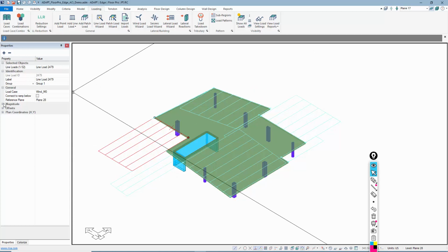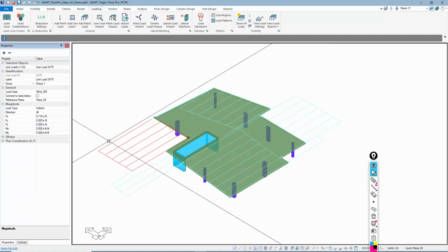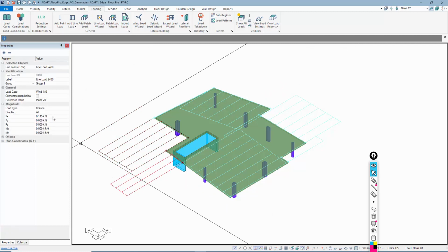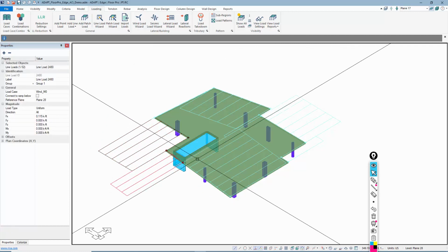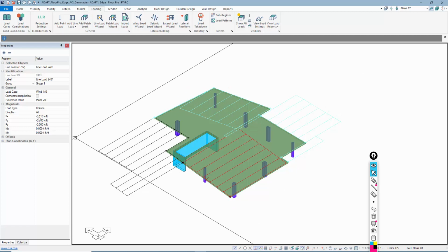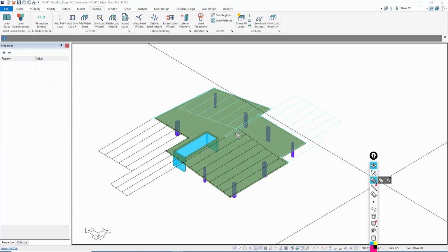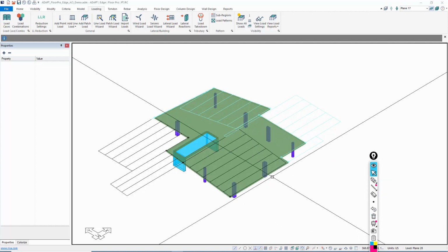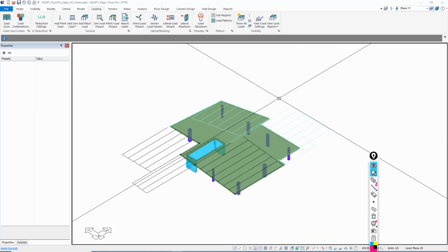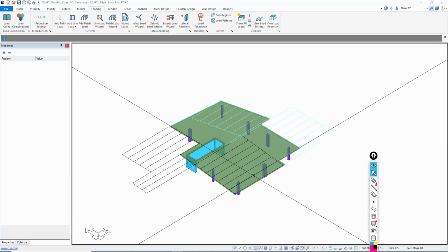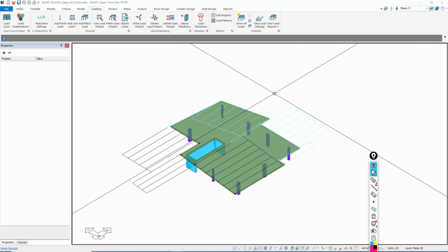This particular load, if we look at magnitude, is 0.116. This is also 0.115, 0.116, and then this is going to be in the negative direction, same magnitude. So we calculate the required moment, and then we actually produce that moment using these line loads, which cause the twisting effect relevant to the input for eccentricity. So that's how the M0 and M90 load cases are established.